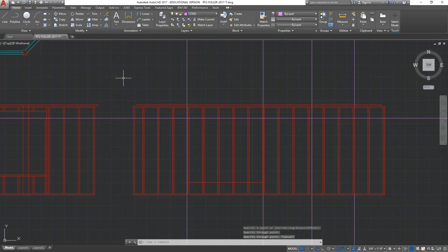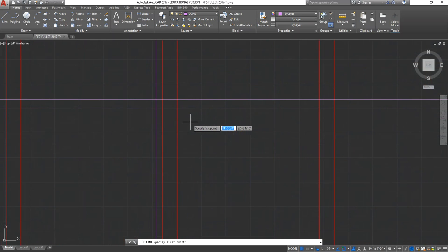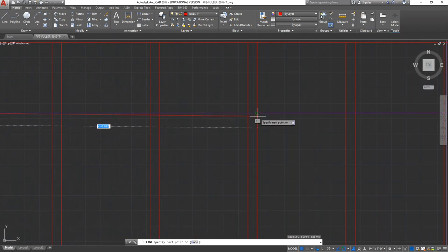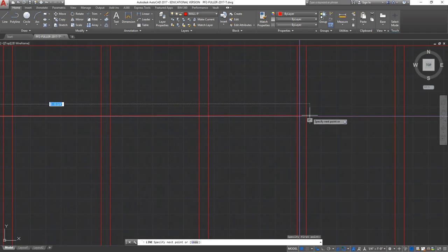That's my window opening. So I'm going to draw another line, get in here, and it's really going to be right there at the corner. And actually I'm still in construction mode. Let me get on the wall plan layer. Alrighty, and start a line again right there at that intersection, and then come all the way over here and meet up at that intersection.